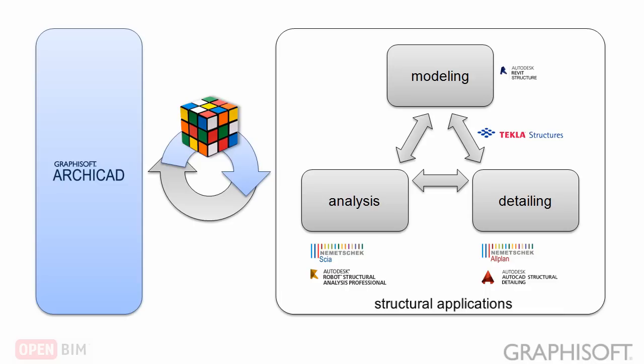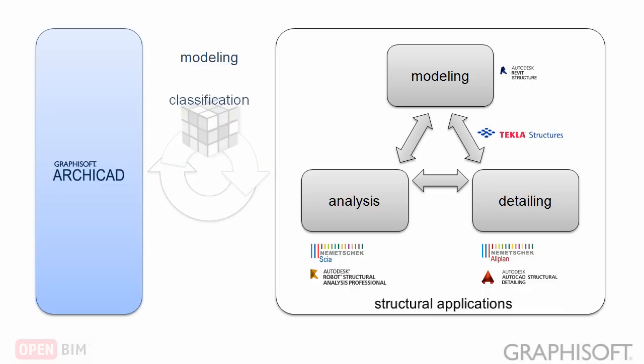This data connection involves more than a simple two-way model exchange. It must be able to manage changes in the models, and this is a cyclical process with many iterations. The main functional requirements of the data exchange: create the model for each discipline, assign types to elements and classify their functions so that the other discipline will recognize my model elements in its own environment, filter elements and data. For export, I should only export the data that the other discipline needs.